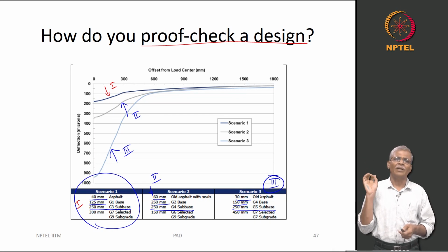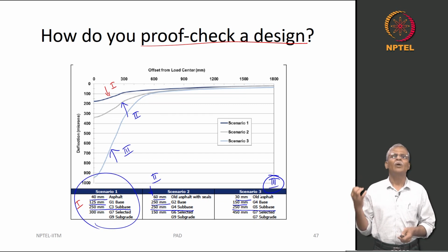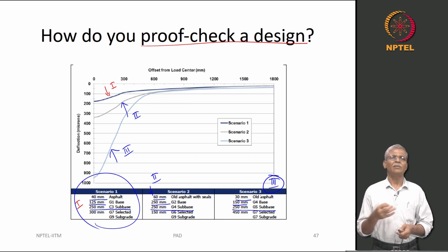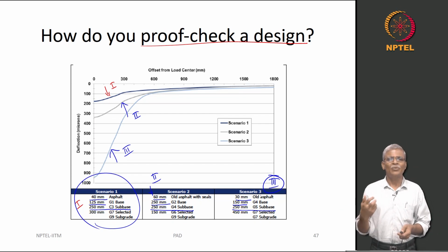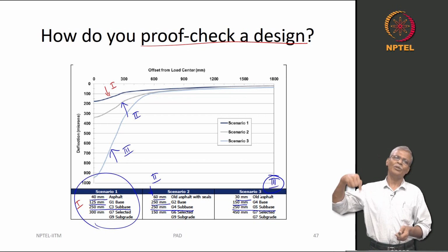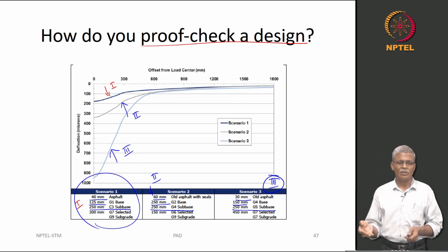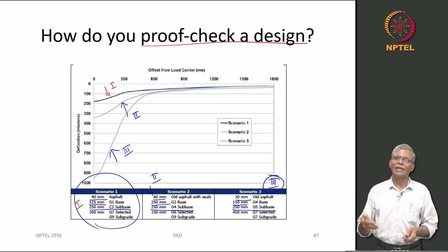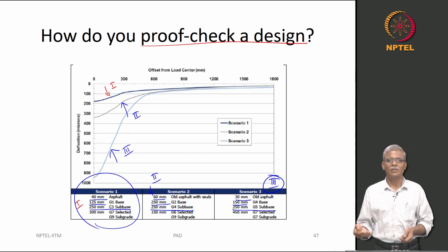how is traffic handled in South African or Australian or American pavement design method? How is the material characterization handled in these 3 countries? How are the distress equations handled in these 3 countries? Okay. So, that means if I give you the axle load spectrum and the material properties, and also tell you the location where the pavement has to be designed, and if you learn these 3 methods and design a pavement, will you get a thickness identical to the thickness that we get when you do it with IRC 37?